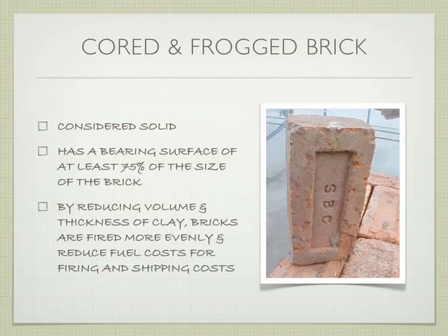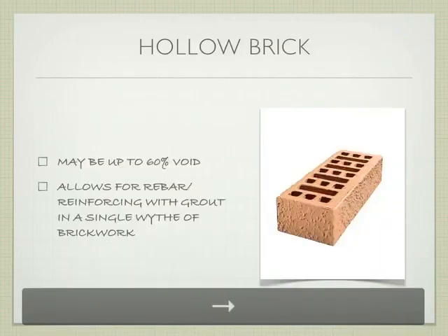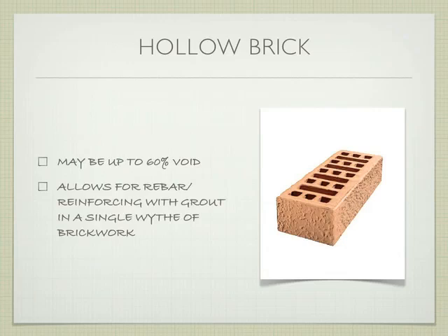And it obviously reduces the firing costs because it takes a little bit less time. So it's a pretty good advantage to this whole system, right? So a hollow brick can be up to 60% void. So we see there's an awful lot of void there, right? It can allow for rebar to pass through the hollow bricks, right? And it can give you a single withe, which we'll talk about in just a second, right?